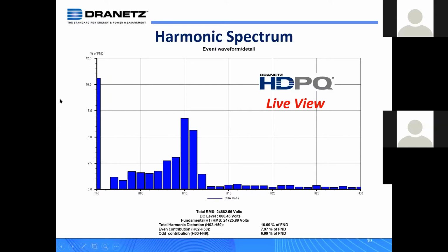An analogy I like to give is when I go measure the voltage in a line plug in my office here, it's 120 volts RMS. So that RMS means that's the one number I can use to reference the voltage here. Okay, so THD is very similar. It's a one number to represent all the harmonic content for voltage on that channel. In a three-phase system, it's phase one, phase two, phase three, and you have voltage and current THD. Okay, so hopefully that was clear.